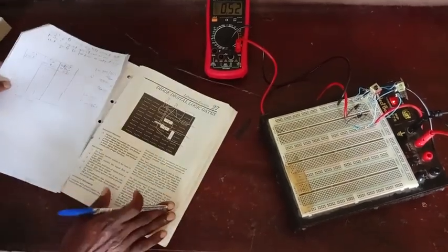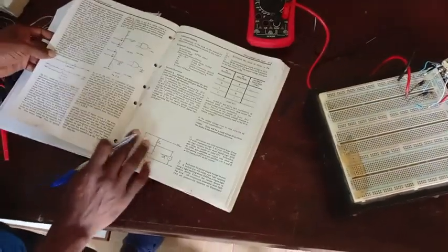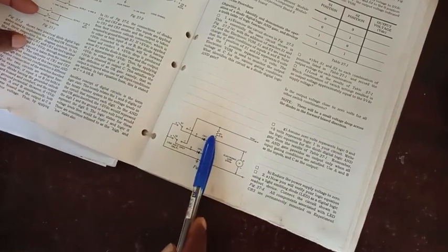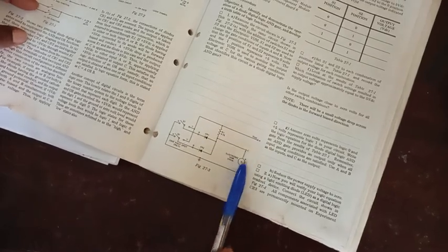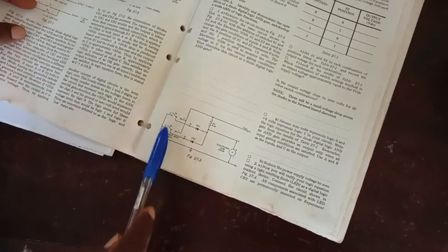For our AND gate, we have been given a circuit here, a diode digital logic gate. We are going to use 2 diodes. Then we need a resistor connected to the source, and a voltmeter to measure the output. Then we need 2 switches, which will serve as our signals: the first signal and the second signal. So switch 1, switch 2.